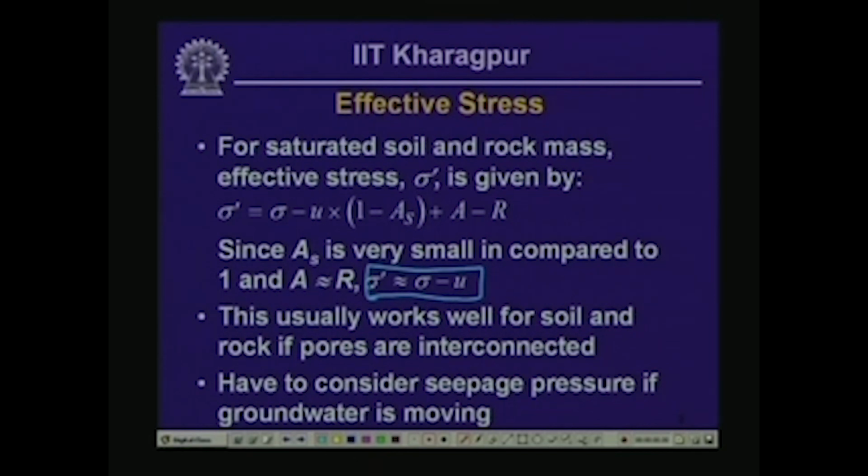So in simple cases, we are going to get the total stress, simply subtract from it the pore water pressure, and then we get the effective stress.